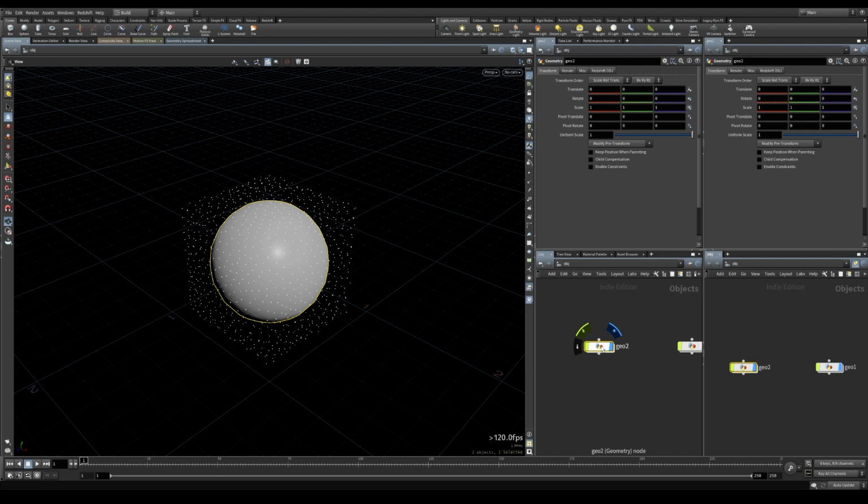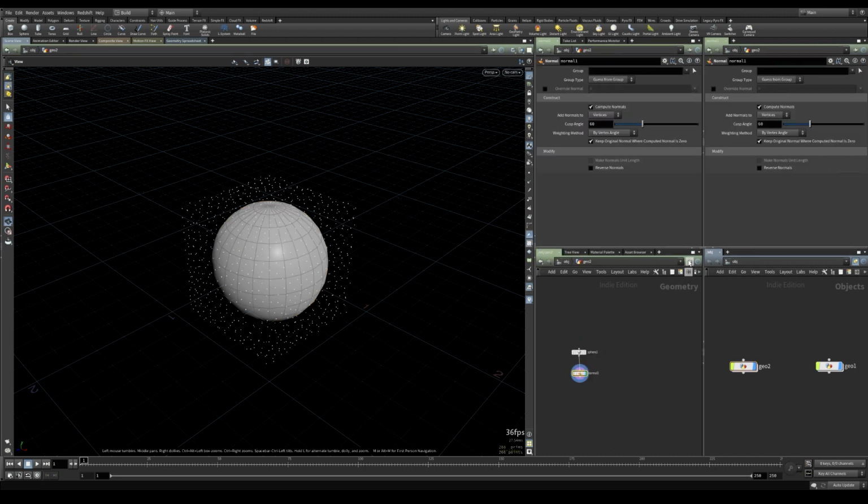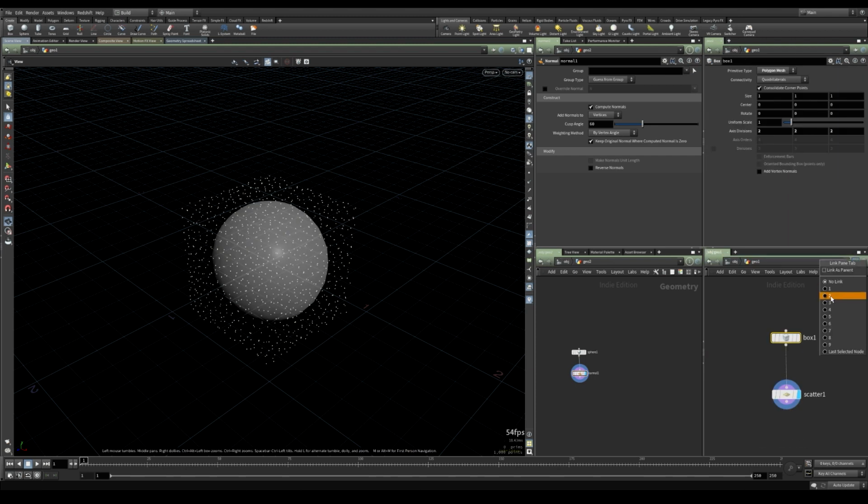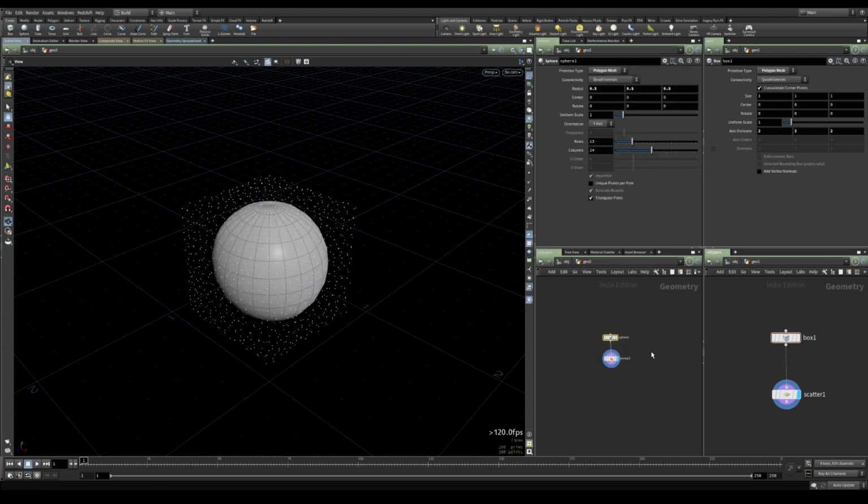Now we dive into one geometry, right click on the pin icon and choose a number, and choose the same number for the parameter window. On the right side, we do it with another number on the other geometry. So basically we have linked the network view and the parameters of different geometry.